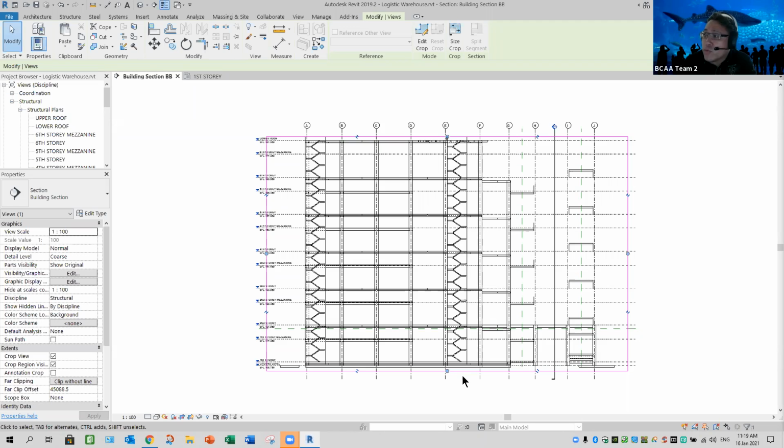Once you increase the scale factor, my model appears smaller on my plan paperwork. Smaller means not clear, and not clear means you need to enlarge certain details, which is not so good. So this box here will save you some time, whether you adjust vertically or horizontally.